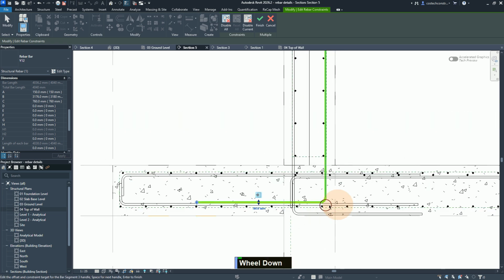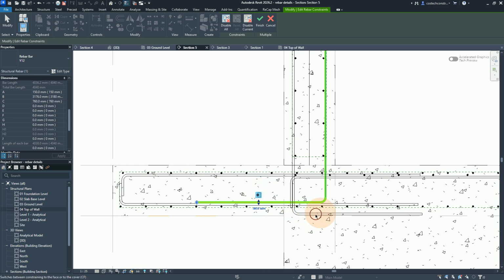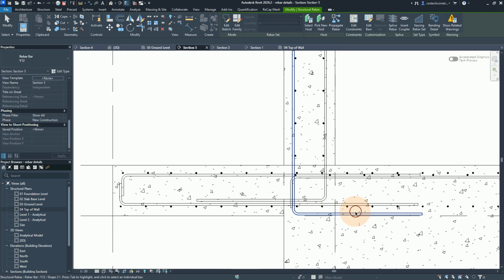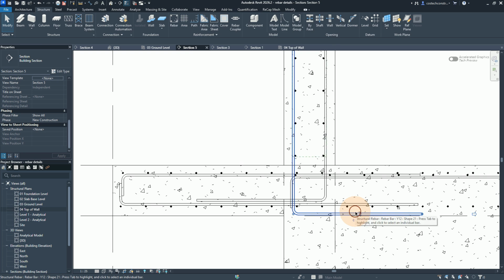Okay, but since now this one will be also for this one, now this one, the -80 will be for this other Rebar Set. We'll also add another 12 here. So we'll give this one -92, then enter. I'll click here to finish. Now I will want to show you the reason of giving here -92. You can hit escape, then select this other Rebar Set.